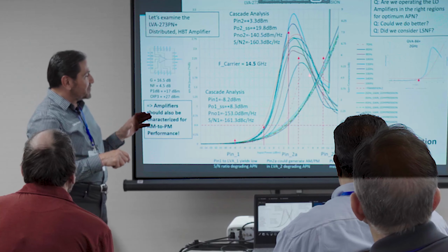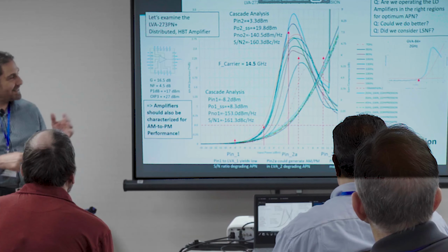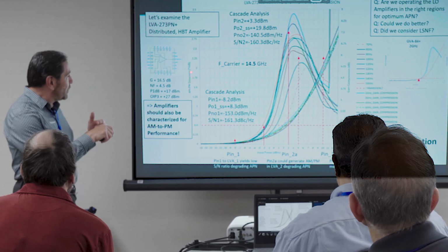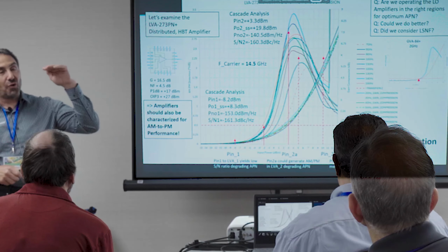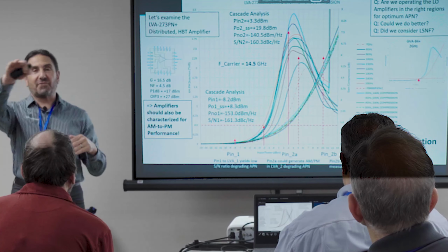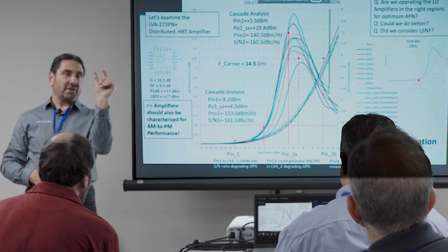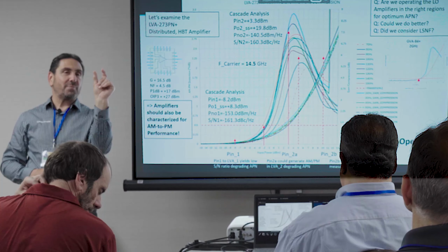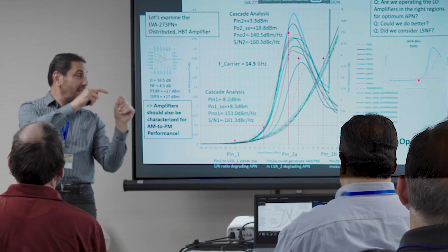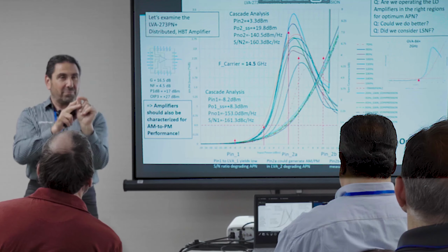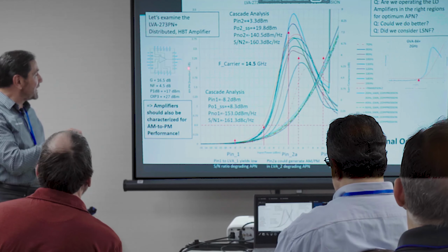The thing that makes it frustrating is not all amplifiers behave alike. This is measured when you look at it as degree per dB. Don't look at phase versus input power. Look at the slope. So take a 1 dB section of input power range, get the slope of that line and plot that, then move it by your next point and plot that. So this is in degree per dB.